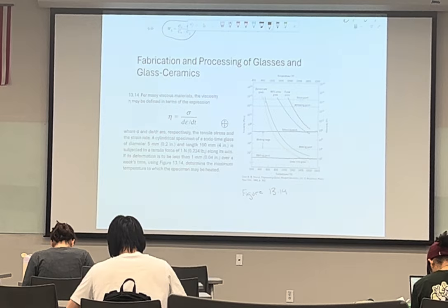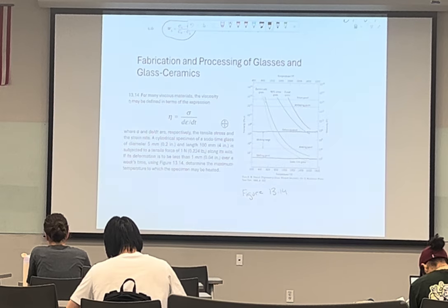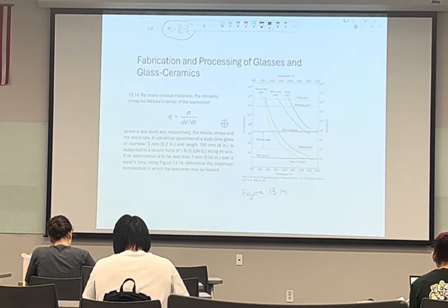And then the final point that they mentioned here was the strain point. So the strain point is at about 3 times 10 to the 13 pascal-seconds. And for temperatures below the strain point, fracture can occur before the onset of plastic deformation, and the glass transition temperature will be above the strain point. So above all this is going to be your Tg.